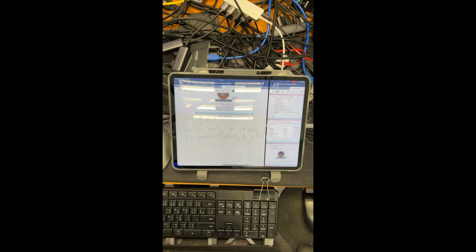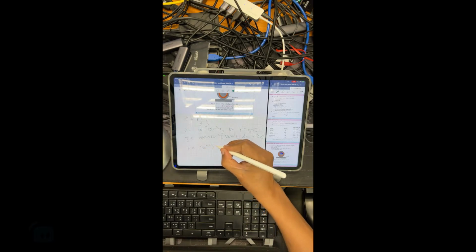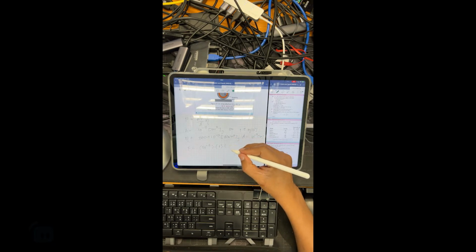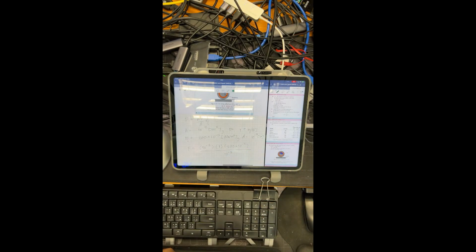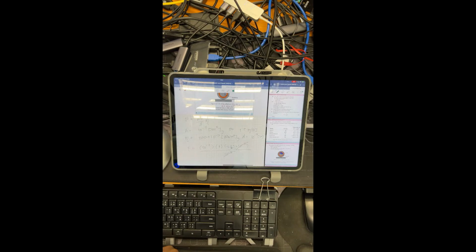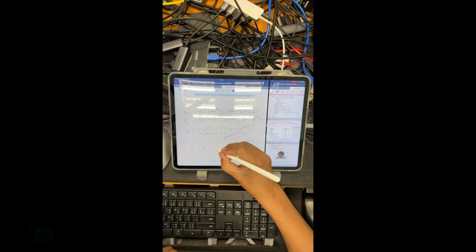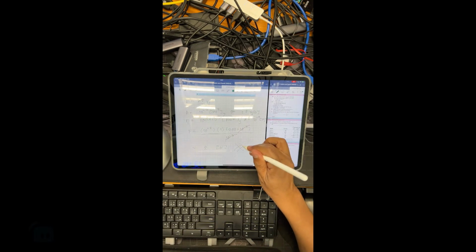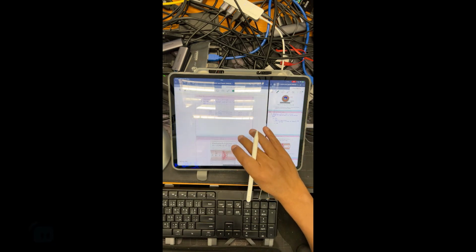So let's substitute everything into this formula, A V by D times eta. F will be A, which is 10 to the negative 2, V is velocity number 1, and eta is 200 times 10 to the negative 3, which is 0.2 actually, divided by D, which is only 10 to the negative 3. So you can cancel these, and if you divide by 100, it's going to be number 2. The force would remain only 2, and the SI unit for force is Newton. That's it for our problem related to viscosity. It's 2 Newton right here, the answer.